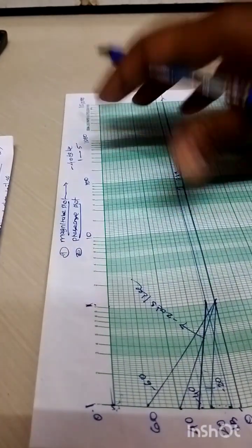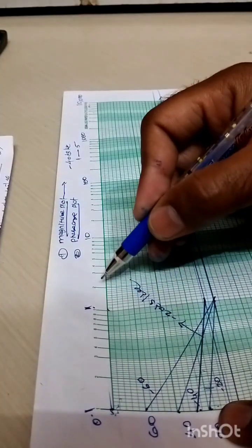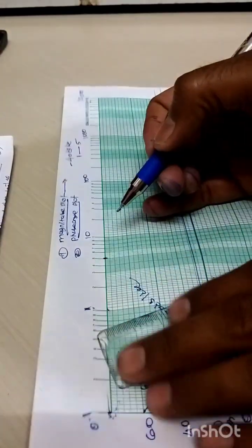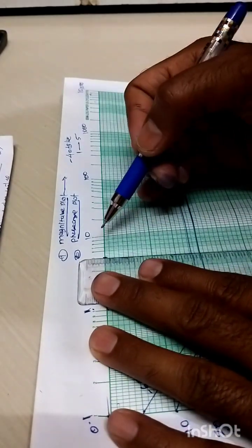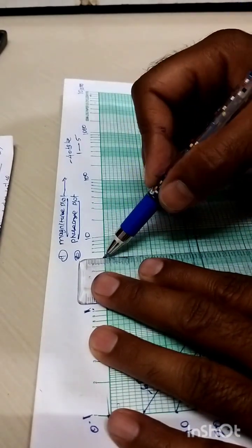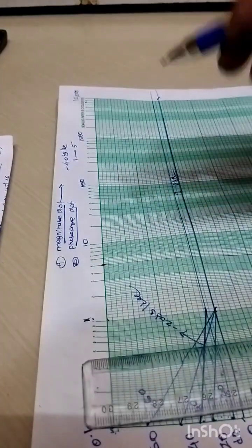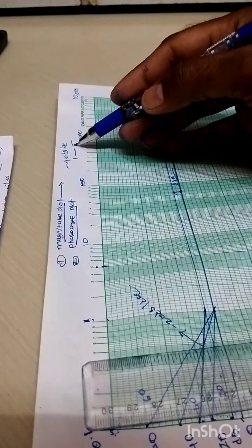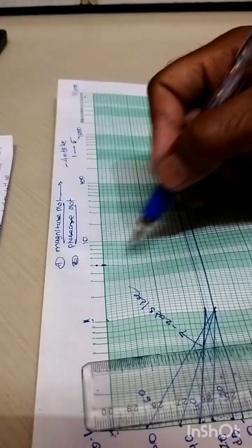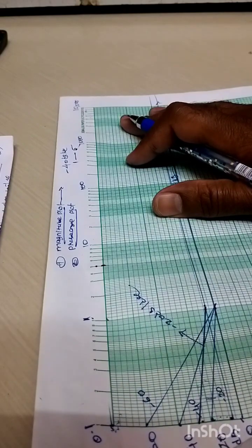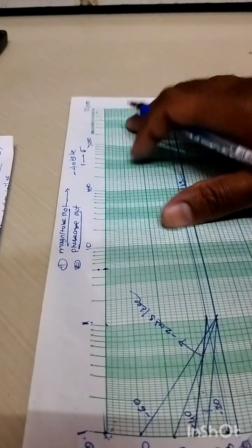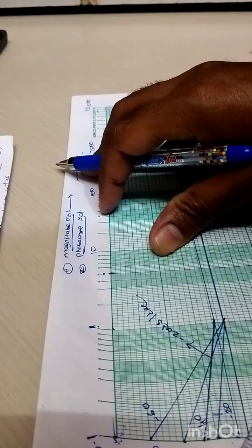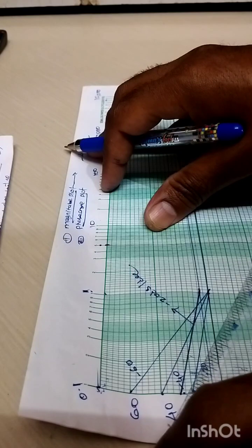Now see, this is the 1 radian per second, this is 2, 3, 4 and 5. I will highlight this particular frequency by putting one vertical line here, right? This vertical line represents the desired frequency, which is exactly equal to how much? 5 radian per second, because this is the end point for this factor, right? So it begins with this 1 radian per second, starting point is 1 radian per second, but whose slope is how much here? Minus 40 dB per decade.